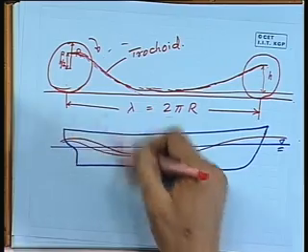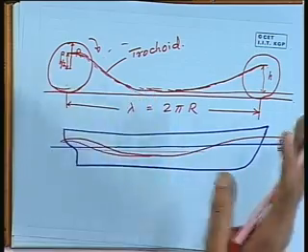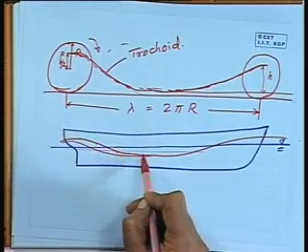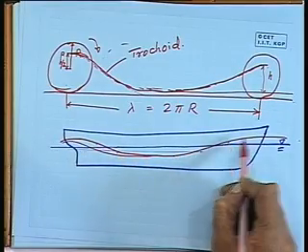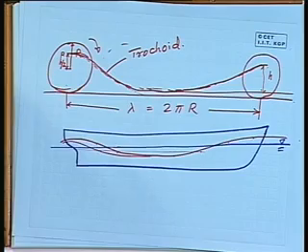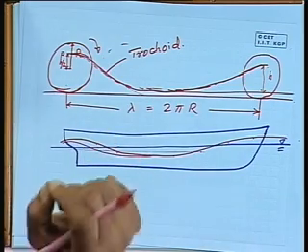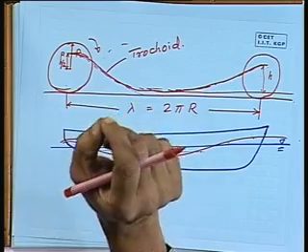This is the first approximation, and then through the buoyancy curve which is drawn at each section, I can take off the area corresponding to this water line or the water height, integrating it towards the length, or that multiplied by the density and unit length gives me the buoyancy contribution per unit length, or the buoyancy distribution, which I have drawn here.